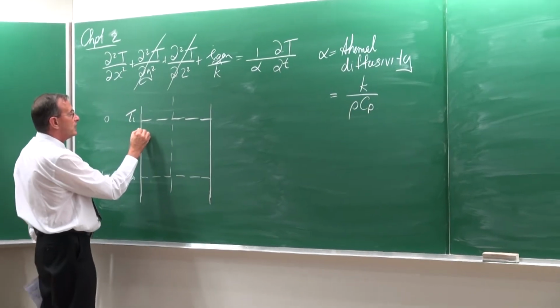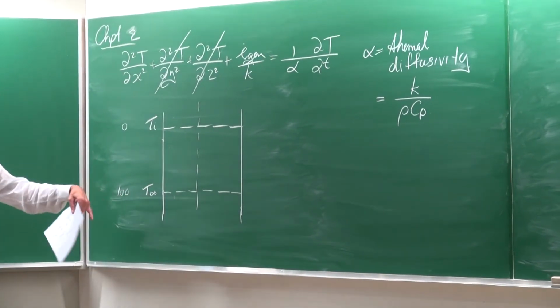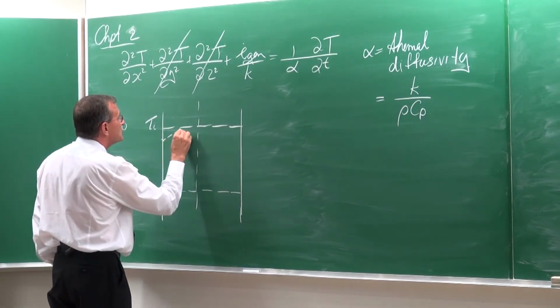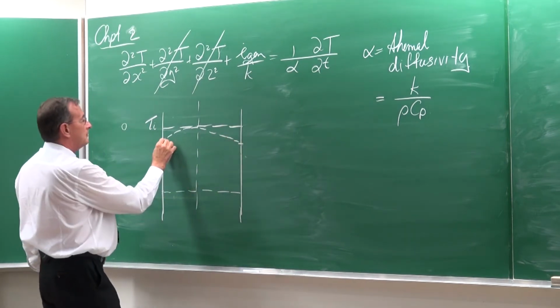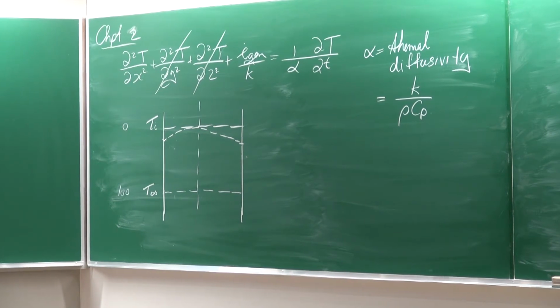Well, firstly, we can expect that the temperatures on the side is going to increase, isn't it? Because they are the closest. So we're going to have a temperature distribution typically like that. And because of symmetry, if it's 100 degrees on this side and 100 degrees on this side, then that temperature and that temperature is going to be the same. Okay?